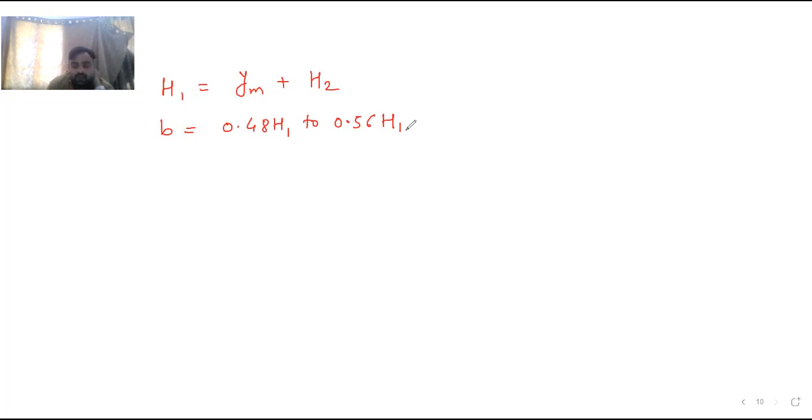Okay. Then length of toe slab. This is also called the toe projection, and it is taken as 0.3 B. Once you calculate B in the above step, if you take 0.3 of that, you will get the toe projection. 0.33 or 1/3, whatever you want, you can do. Either you do 1/3 or take it as 0.3 B.